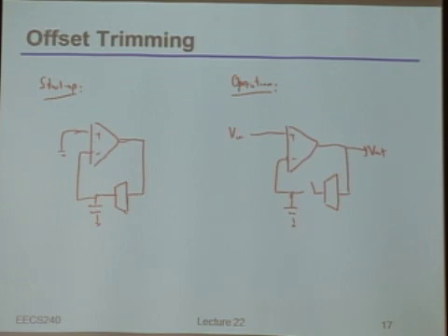Now, by the way, where do you lose that charge? What's the most likely culprit for that charge leaking away somewhere? Through the switch, right? Unless you have a zero leakage switch, which, okay, there are some crazy people, including me, who tried to build those kind of things, but don't worry about that. That's not reality just yet. Unless you have a zero leakage switch, there's always going to be some current flowing through there. And eventually, the voltage on that capacitor will not be what it was supposed to be. It'll leak off to something else. Okay, that kind of sucks.